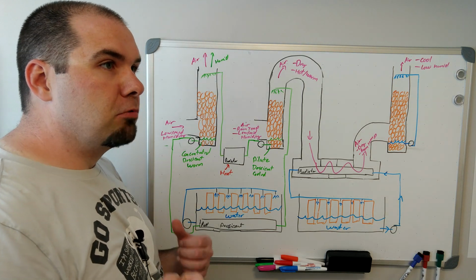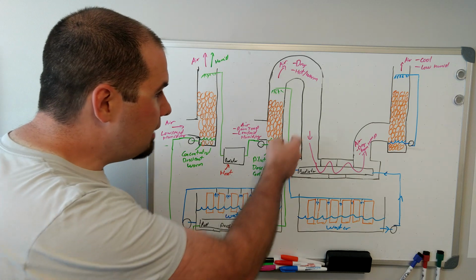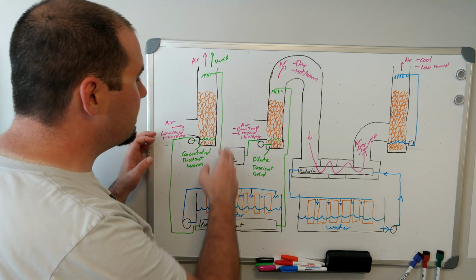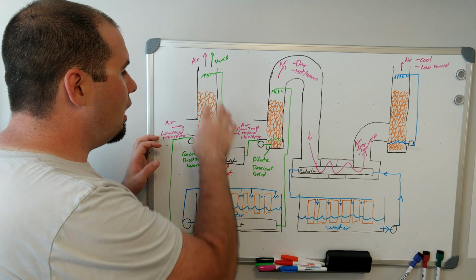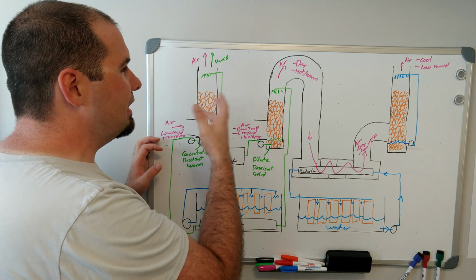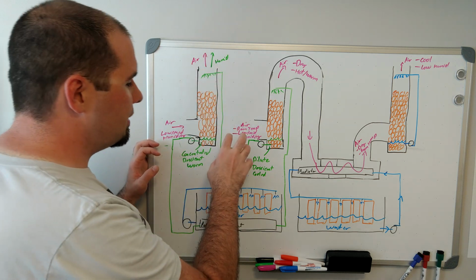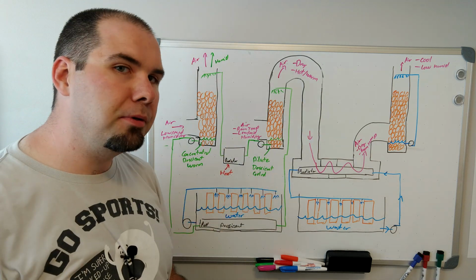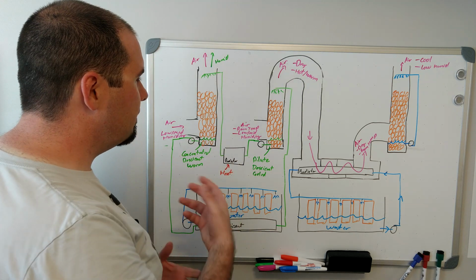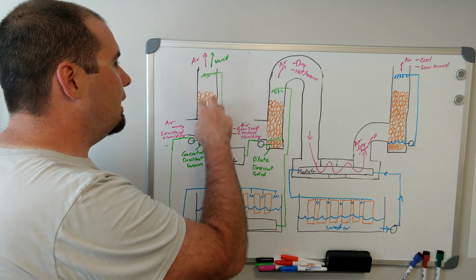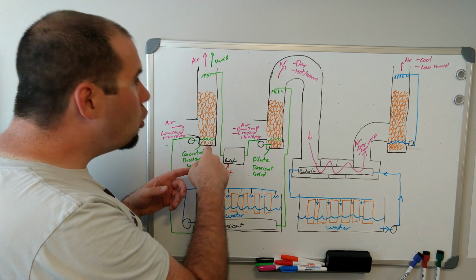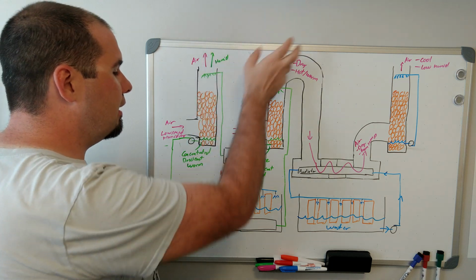In order for it to release that water so that we can keep using it, we have to heat it. Because when we run it through this process now, it's hotter than the air that's going through it and can easily release that humidity. So when it's hot, it's not going to act to take out humidity as much. So by heating it up, I think he showed about 40 degrees, maybe 50 degrees Celsius, it allowed the air that was flowing in, that is medium to low humidity, to be cooled, but then become very humid because it's taking a lot of that water with it.